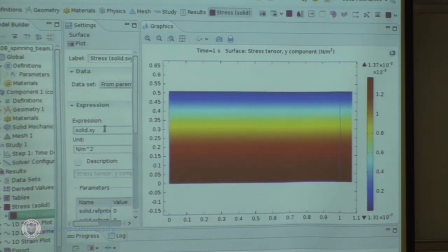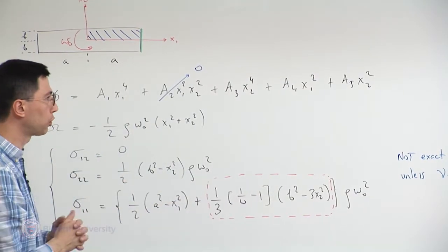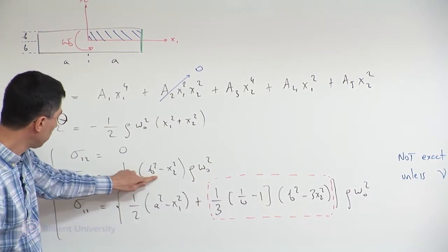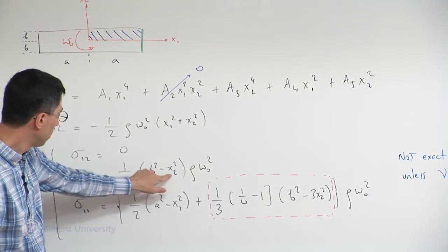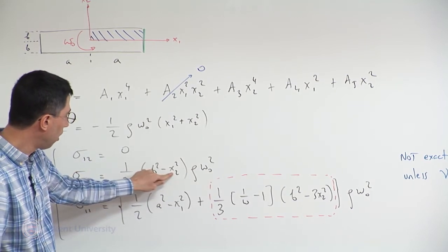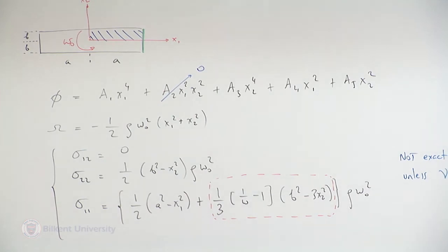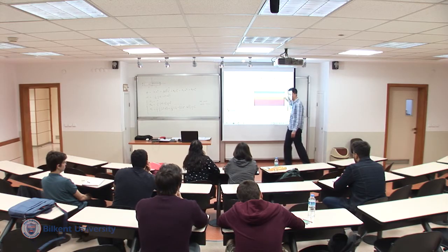Okay, and now what you see is, right, so it's nu is equal to 0. Omitting the red rectangle, I should have the exact solution, right? So the exact solution suggests that sigma 22 is a function of x2 alone. And that's what I see here. There is a variation only along x2, and I don't see a variation along x1.